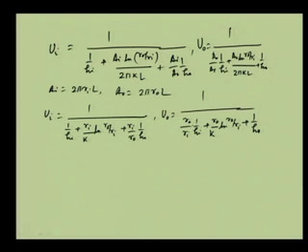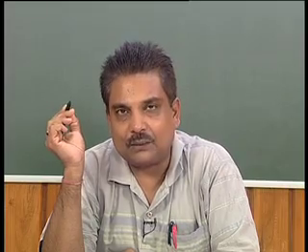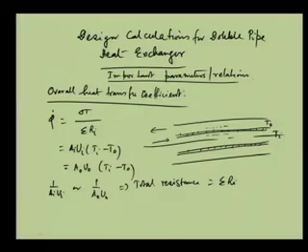Now, here one thing we have not taken into consideration, which is called the scale factor or the dirt factor, whatever it is, that happens due to the deposition of scales on the surface of the tube. As we have seen in the first case, there is a tube and there is a possibility of additional resistance due to formation of scale on this surface and on this surface.